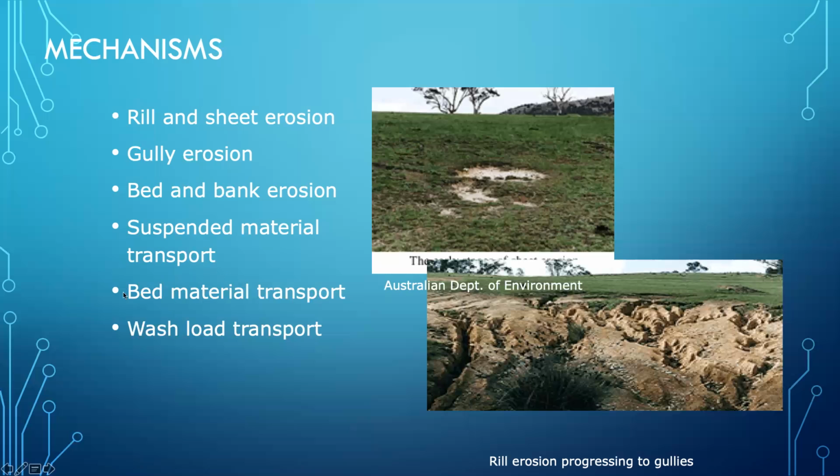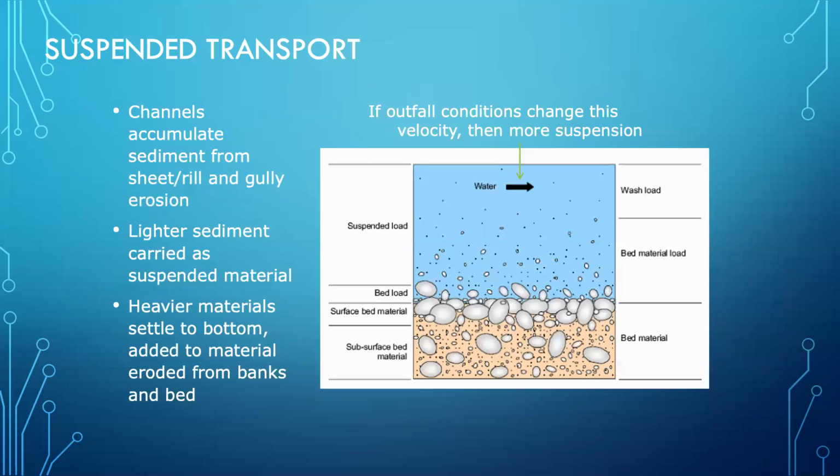And then bed material is, you can think of the bottom of a channel as a slurry bed. So mostly solids with liquid lubricating everything. And that slurry moves as a bed material. And it'll stop moving depending on what the overlying velocity of the water above it is.